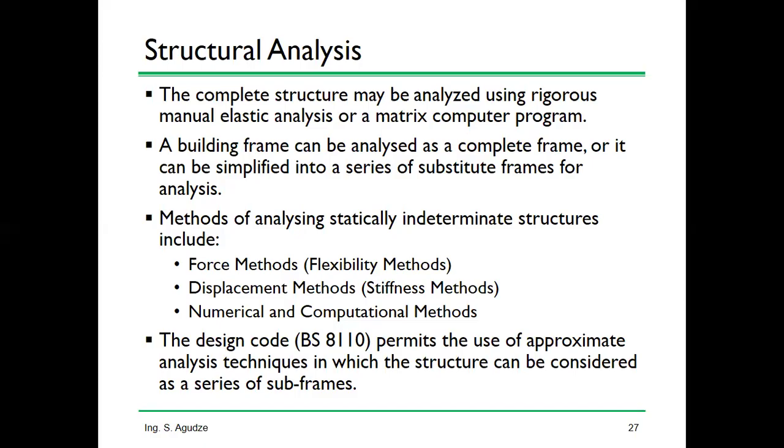And for the purpose of simplifying the design process, you may have some books that have also given certain arrangements and different kinds of beams and loading arrangements. They will provide some factors. If your beam looks like that, you can use those factors to generate your bending moment and shear forces. And then it will save you from rigorous analysis and so forth.